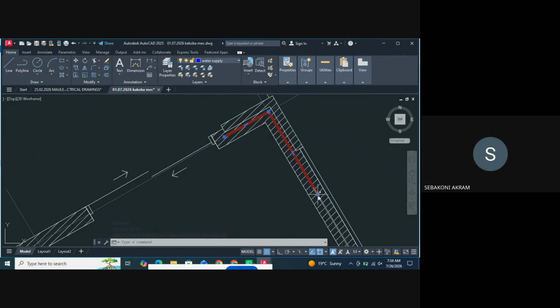Or you can add from this point here. You first highlight it, you select it like that. You come to this corner here. You don't click on it, you just put the cursor there. That box comes around this one. So you add vertex, then you move in the direction you would want. Add vertex enables you to change directions, you see it? So that's how you work with this polyline.